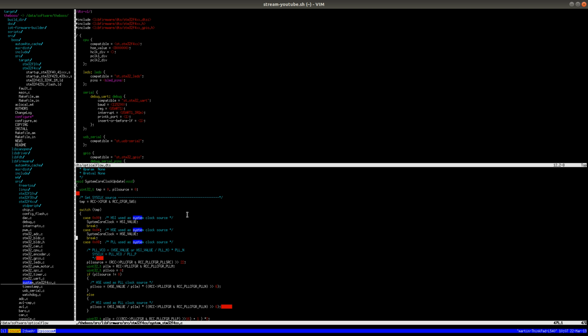The idea is that this variable is supposed to contain the frequency of the main clock, but it's kind of deprecated because there is also code in the STM32 RCC implementation which does exactly the same thing. It gets you the core clock, but it also gives you all of the other clocks that are used in the system. It's called RCC get clock state, or get clocks or something, which is the function that I would prefer my code to use instead.